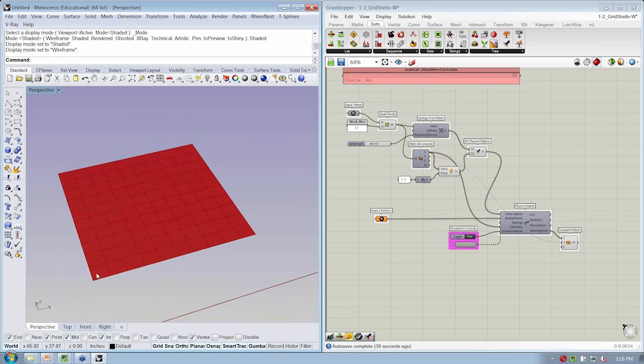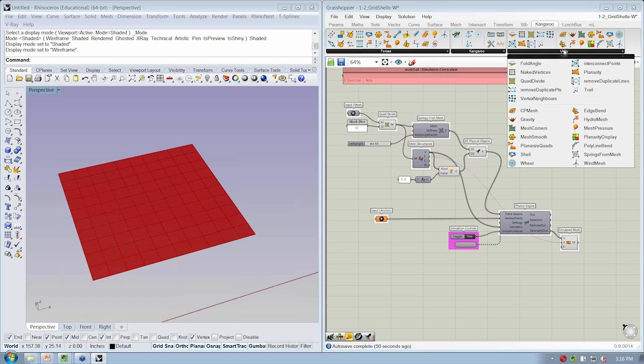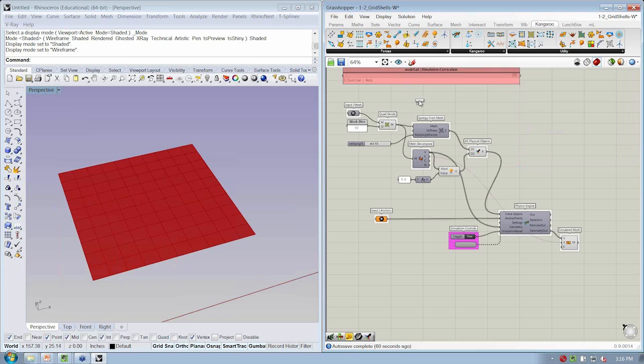And just let them be pulled from the mesh without having to actually specify them in Grasshopper. So if we go over to the Kangaroo tab, under Utility, there's another nice object here that allows us to get the mesh corners from the boundary, right? This is based on a threshold. So let's go ahead and drop this object into the canvas.